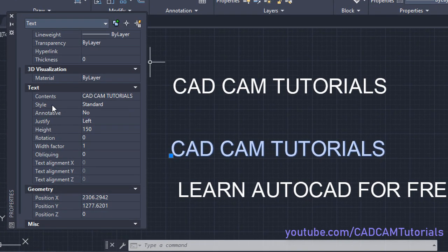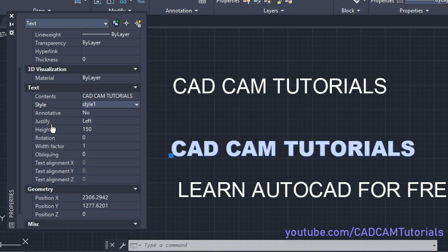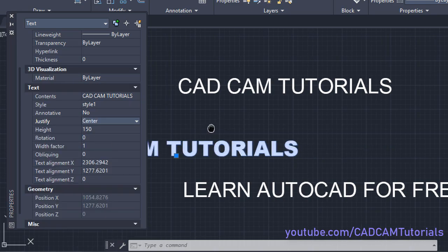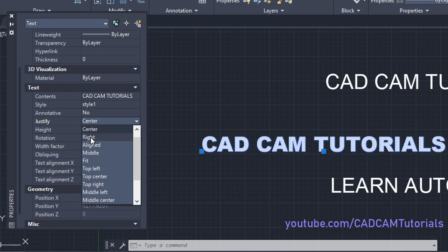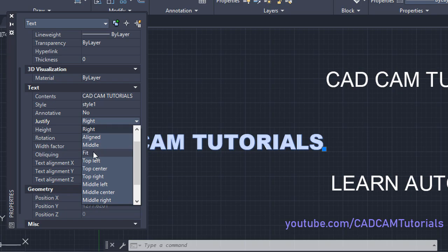In this properties window you can change contents, then you can change style. Suppose I want the style to be style 1. Then you can make it annotative. You can change justification. Now it is left justified with respect to this insertion point. Suppose I make it center, then it will be arranged center around your insertion point. Same way, suppose right, it will become right. Suppose I will keep it left.